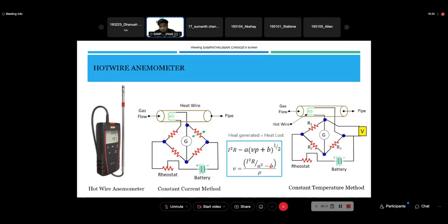So every time you are using an anemometer for research or experimental purposes, the best thing you can do is first calibrate it with a standard instrument which can provide a uniform, well controlled flow, and a standard velocity measuring instrument which can measure the velocity accurately. Then we will compare both of them. The same procedure we are doing in this particular experiment today. Okay, any questions?